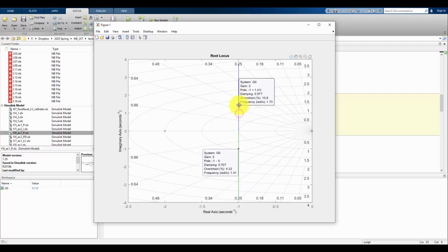The pole placement is going to determine the natural frequency and the damping ratio. If I look at some of the axes that are coming out here, the angle here is telling me about the damping ratio. So if I'm closer to the x-axis, or the angle is smaller, my damping ratio is going to be higher. So here I have a damping ratio of 1, and then this line 0.86, 0.64, etc. So the bigger angle I'm making with that x-axis, the smaller my damping ratio is.